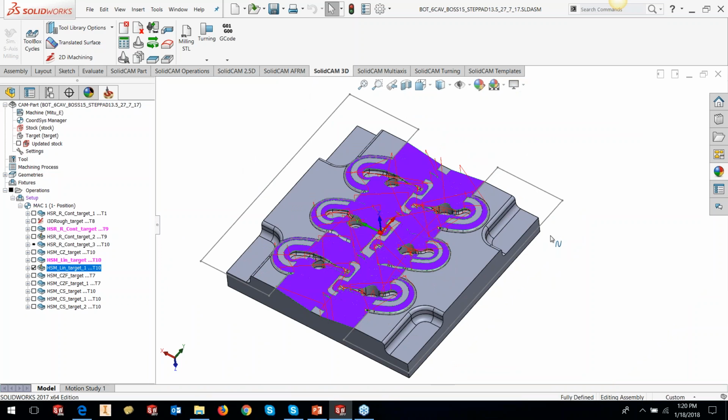This could save you real machining time in the real world on the machine, anywhere between 10 to 15%. So even if you have created a toolpath which doesn't look optimized, you can use toolpath editing to optimize it, remove unwanted areas, and only keep those areas where you think the tool should run. All the other areas, you just chop the toolpath out.